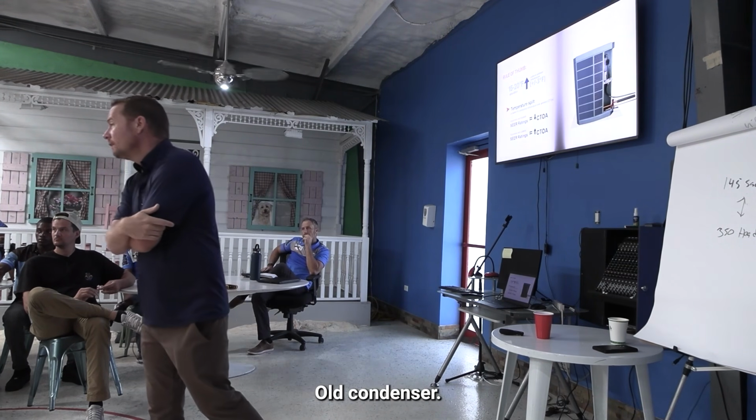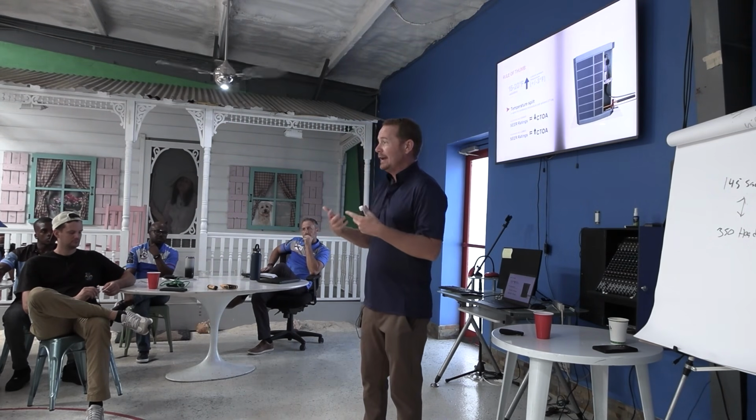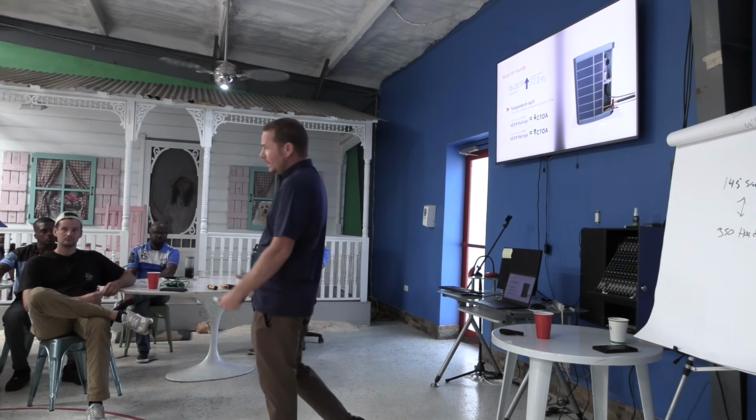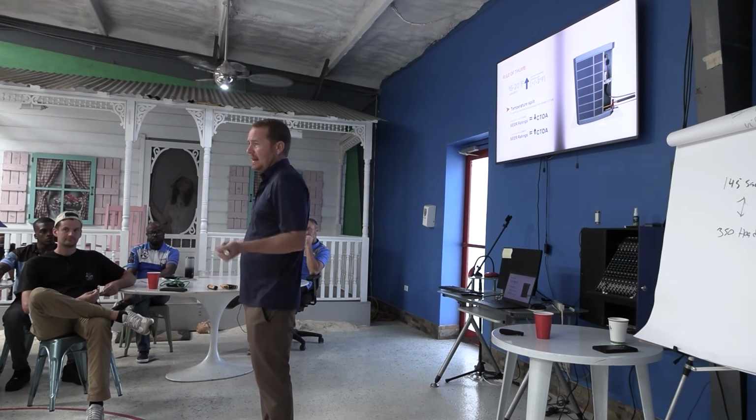Could be an old condenser, right? The fins are falling off. It's in really bad shape. You can't always clean these things to perfection, especially in salt air. But it's having a heat transfer issue out of the condenser. That's really what it's telling us. We're not getting the heat out of that condenser.